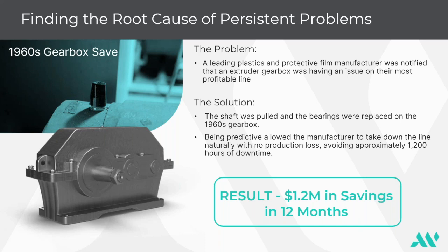So with seeing this in the vibration signature, and also one times impacting within the time waveform, seeing all this within the vibration data, I made a call out: hey, let's check this coupling out. Let's do a lift test on this gearbox input shaft. Out of that, they had some scheduled downtime that came up where they were able to identify that, yes, this was in fact the issue.